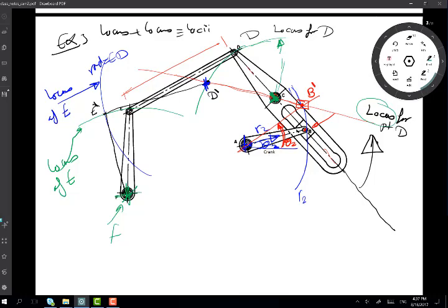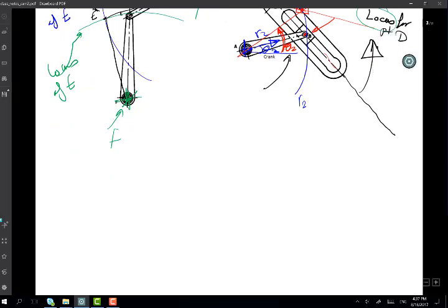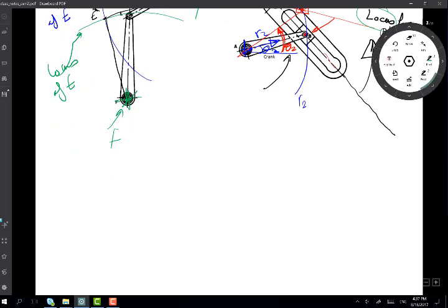So at this point, I have done my graphical solution, and just based on the one value of theta2 at this end, I could find where every point is in the linkage based on this motion, and hence it's really a single degree of freedom linkage, and that's why it's possible to do that. Now, another example, I'll put here in front of you.